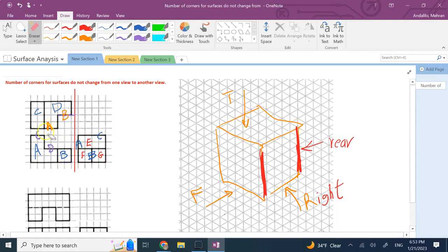What about D? Well, if I use projector rays and I transfer D using the same method I did for B, so here I have that ray and this ray. If I use the 45-degree angle and come down, then you will clearly see it is going to get the entire depth of the object. Now, which edges have the entire depth of the object?